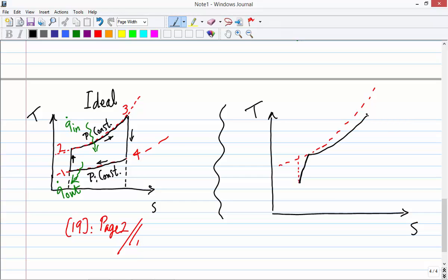like that. And again, if the next process was isentropic, we expect that to be a straight vertical line, but it's not. The entropy is going to increase. So we go off like that. Entropy increases. So from this entropy, we end up at that entropy. And again, the pressure should remain constant, but it's not going to be constant. It drops,